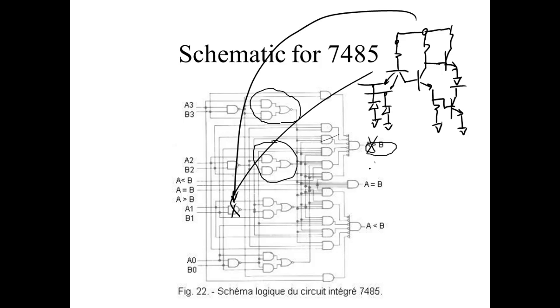So this is definitely a combinational logic circuit, but if you look at every symbol inside that, it's made up of nothing but the basic gates. And of course here they're drawing these as negative NAND, but actually they're NOR gates, right? You understand? But in this circuit, these guys are looking for all lows to get a high. They're not looking for any high to get a low, right? You understand? But I'm not concerned with that. All I know is if the two inputs are equal, so if somehow I could come up here and put equal inputs on this thing, and this right here does not do what it's supposed to do, then I would replace the whole integrated circuit. Right?